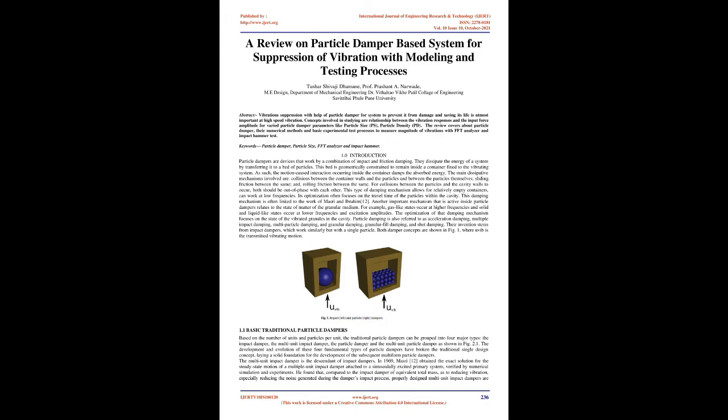Another important mechanism that is active inside particle dampers relates to the state of matter of the granular medium. For example, gas-like states occur at higher frequencies, and solid and liquid-like states occur at lower frequencies and excitation amplitudes. The optimization of that damping mechanism focuses on the state of the vibrated granules in the cavity.